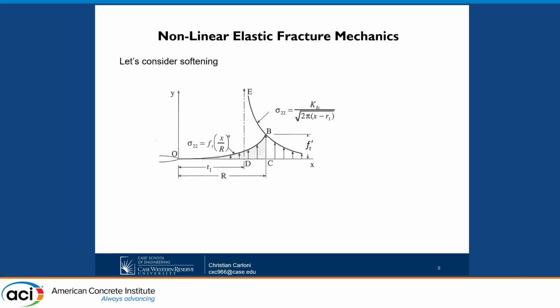So why am I saying all this? Because if you remember that picture of the stress getting really high near the tip, now you have a problem. The stress will never get high near the tip because you will have the softening. So basically what you have is that the stress goes high far from the tip. And then you have all this softening part near the tip. And we call this part here basically the fracture process zone.